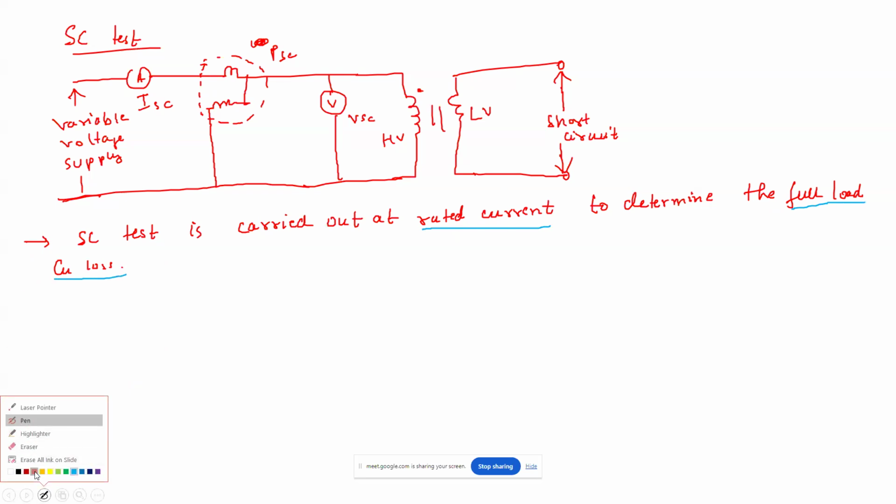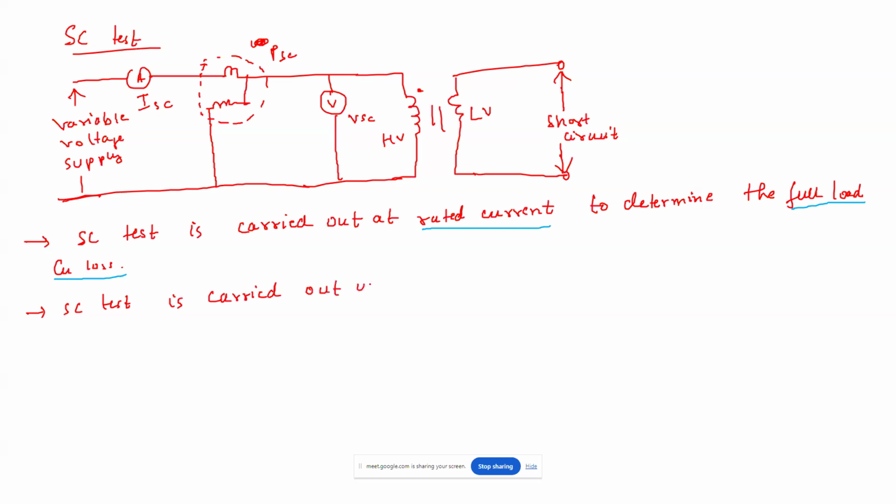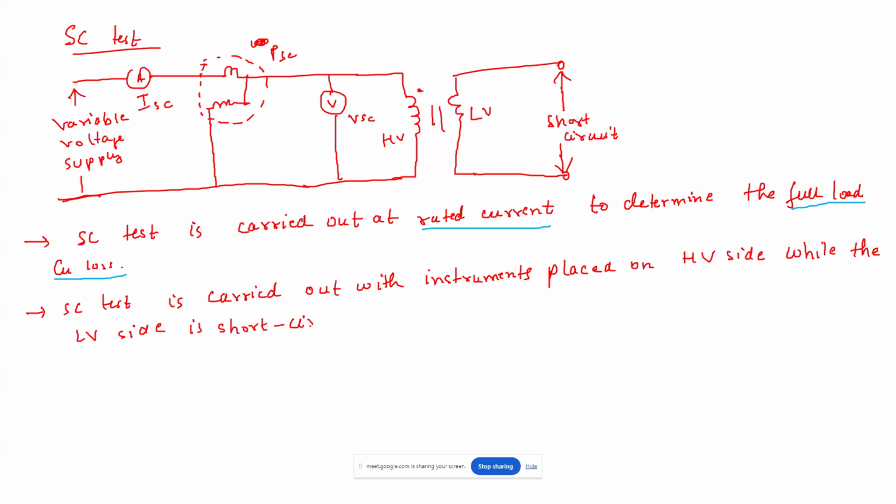Now, the short circuit test is carried out with instruments placed on the high voltage side, while the low voltage side is short circuited. So that is the thing.